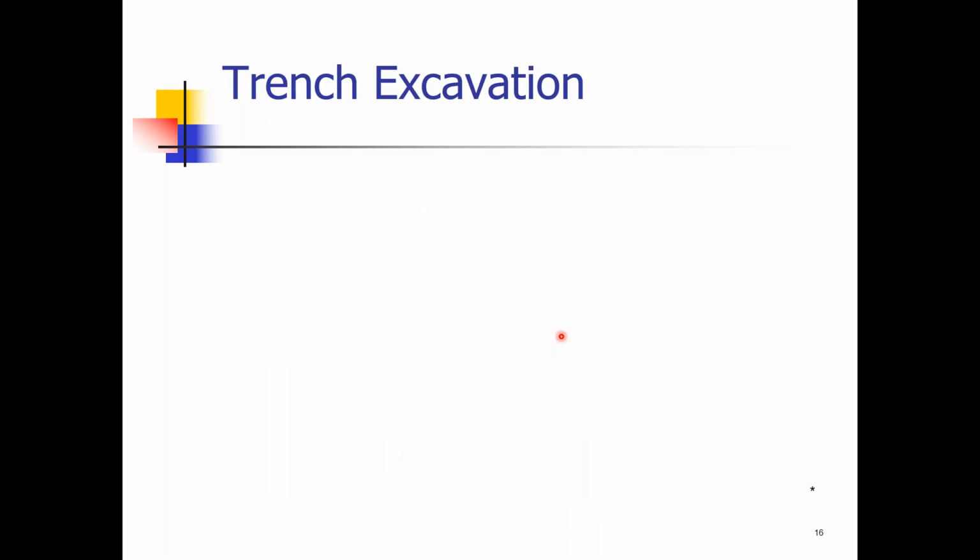When we go to excavate, and again, this is not a trenching and shoring course, but I do want to touch on it just a little bit. Make sure that before you start excavating, you know what's there before you start trenching. Make sure as soon as you're done excavating the area that you start putting that pipe in as soon as possible.